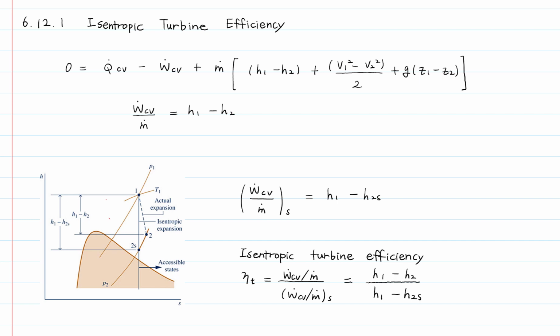First, we are going to take a look at turbines. A turbine is a work-producing device. It converts the kinetic and potential energy of a fluid to useful work. A turbine may be considered a steady flow device. It means that the states of the fluid at the inlet and outlet remain constant with time. For example, mass flow rates and properties such as pressures and temperatures at the inlet and outlet are constant with time. The energy balance can be simplified for steady flow turbines.